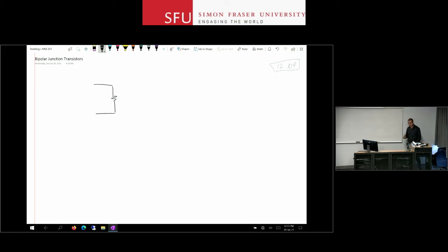So it's an analog circuit. The input of that analog circuit can be modeled with an input resistor, right? And this is your command. This is your input signal. This is what it takes. Then I'm going to use a current source here, but you can probably come up with an equivalent circuit or an equivalent system for a device that is using a voltage source here. But the reason that I use a current source here becomes clear very soon.